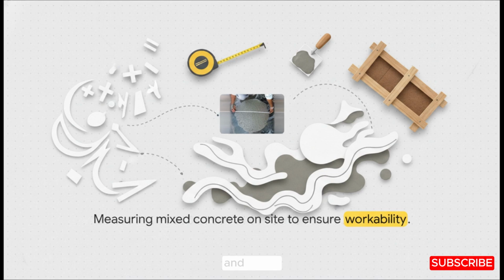Engineers measure the spread and slump of the fresh concrete because, let's be honest, a perfect design mix on paper is totally useless if it's too stiff to pour or too watery to hold its strength. We use these physical tests to confirm that our mathematical design behaves exactly as predicted out in the real world.